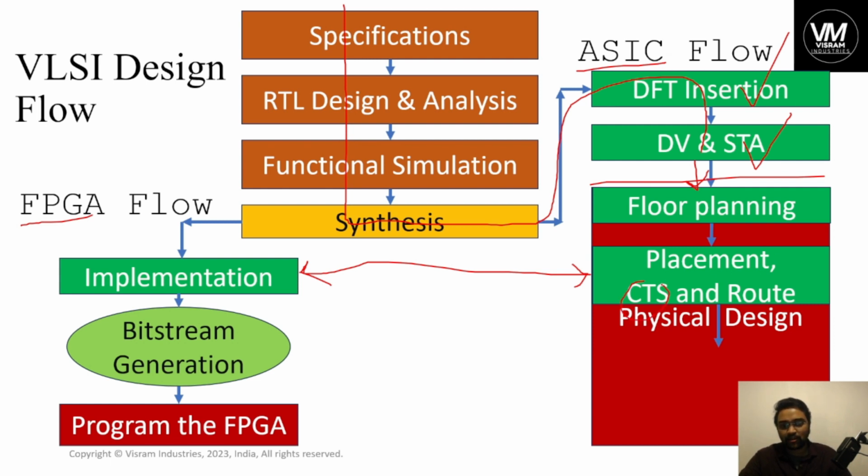CTS is nothing but clock tree synthesis. Whatever clock you have written, those clocks are generated and connected through the different logic cells that are attached. So now the physical appearance is happening. Think of two things, guys. Whatever you have written on paper should be available in the physical environment.